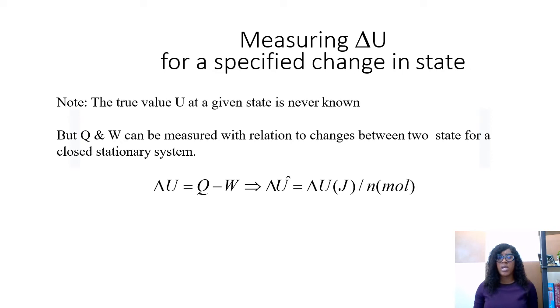But what happens if we only have, let's say, our work, and we want to calculate our heat? How do we come up with our internal energy if that value is not given in the problem or in our system? What we have to look at is our specific internal energy. By examining our steam tables at the different variables, whether it's temperature or pressure, etc., we can look up our internal energy, which would be our specific internal energy.